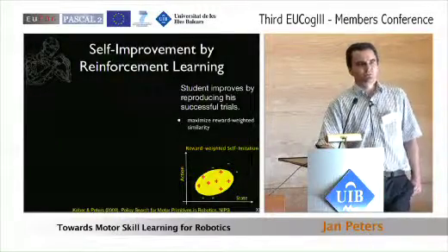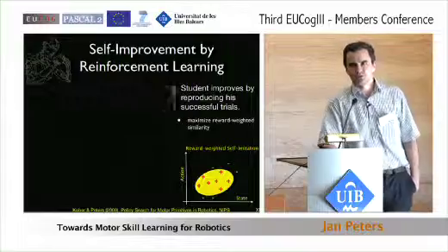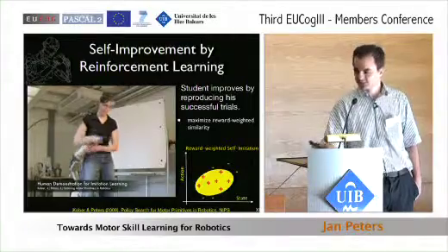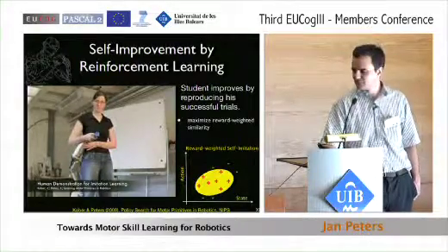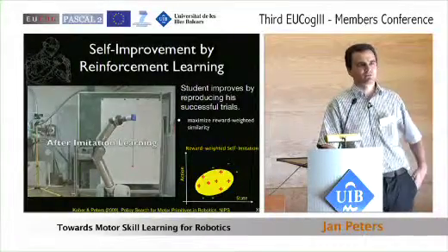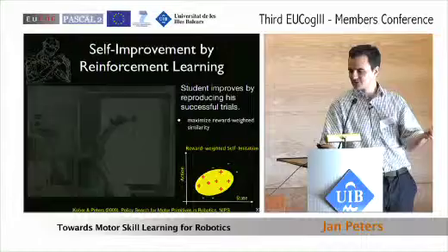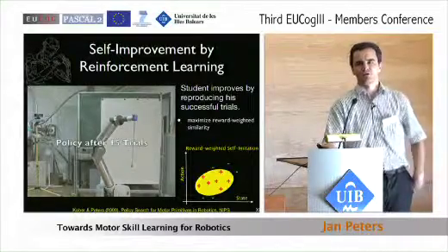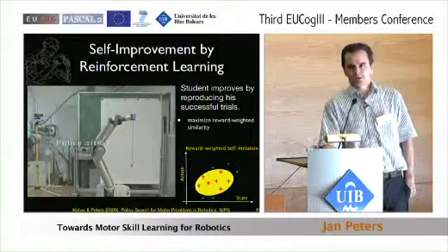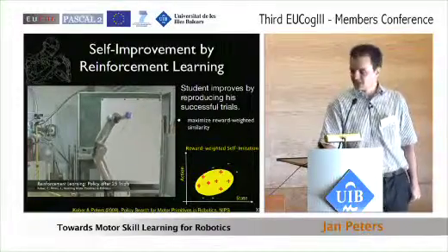Here, you first see that by starting out with an imitation, we can limit the search space sufficiently that we can actually do efficient reinforcement learning. And you see again how we have demonstrated a ball-in-a-cup movement. And the robot, in this case, fails to reproduce this movement. Why is this? The obvious reason is that a human being can produce very, very high accelerations, so it's relatively easy to jerk the ball into the cup. Robots, on the other hand, need to create a desired torque, and this desired torque cannot produce the spikes needed to create this jerking movement that nicely.